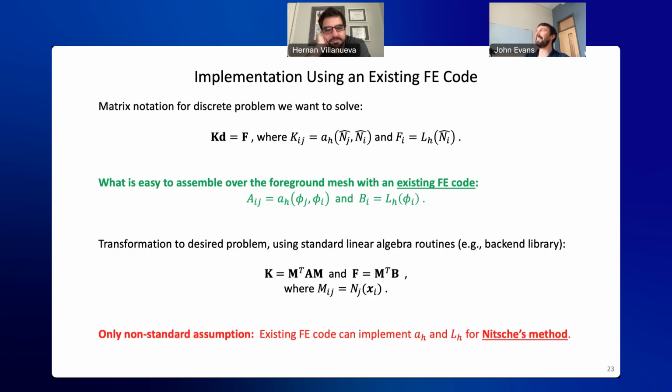Trying to convert a B-rep into an implicit representation, to give you an idea: if you take a bicubic NURBS, right, and you then want to know what the representation of that object along any curve in the parametric space of that object, it is degree 108.